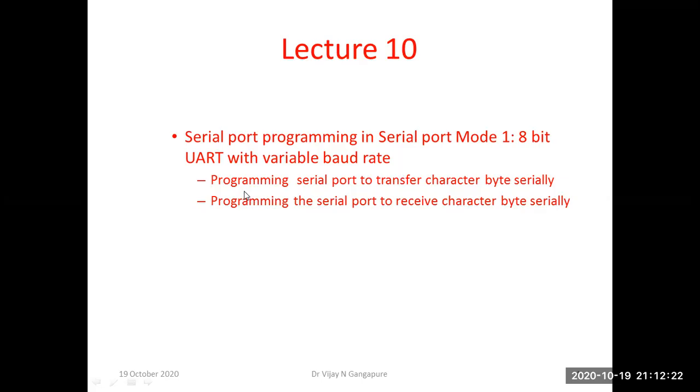So we are going to program serial port of 8051 to transfer character bytes serially in this mode, mode 1. Similarly we are going to program the serial port to receive character byte serially in the same mode, mode 1, that is 8-bit UART with variable baud rate.